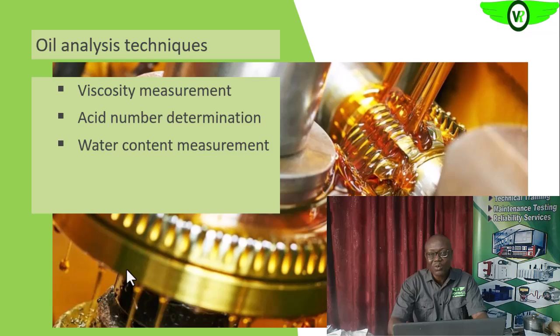Then the water content. That's also to determine the contamination level. We know that if there is water ingress into the lube oil, it will affect the viscosity, change the chemistry of the lube oil, and increase the oxidation of the engine parts.